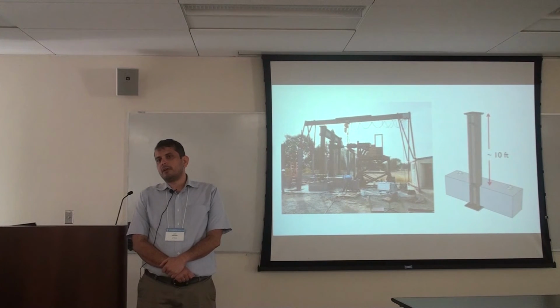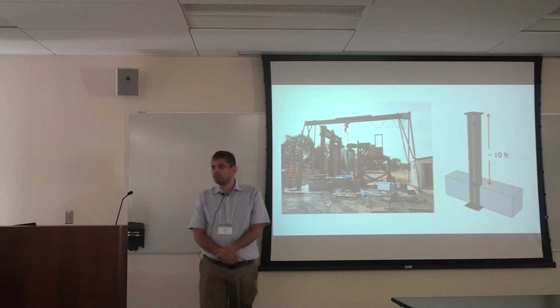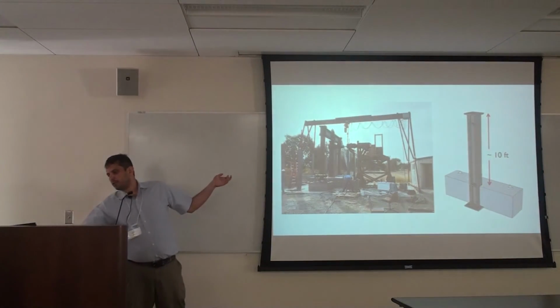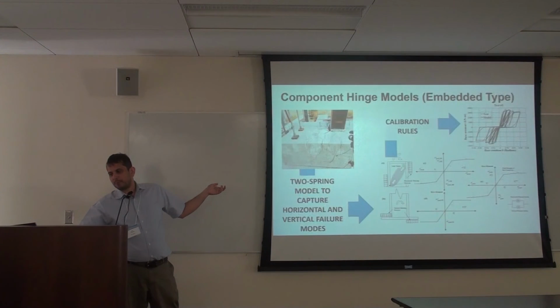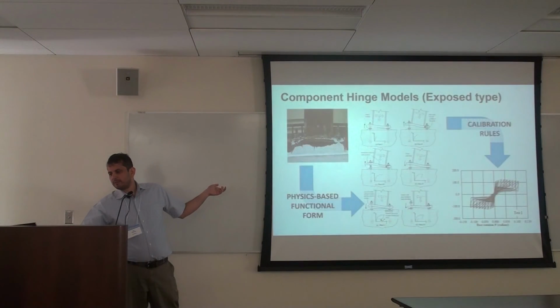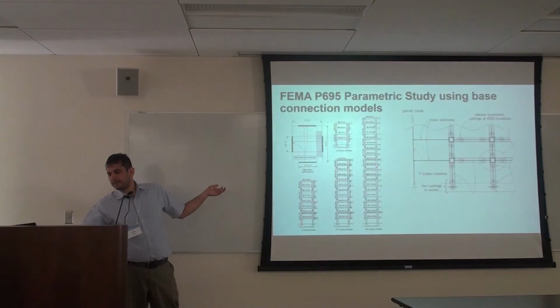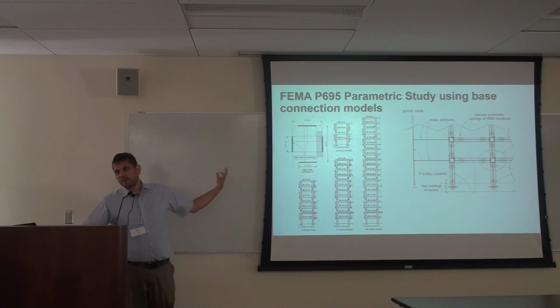Airports are lower rise structures. In terms of the actual clear spans, our 4-story frame isn't significantly different from what you would have in an airport. I think it's a 30-something foot span in the airport, and our 4-story frame is pretty consistent with that. And for that, we actually find that the effect of having the weaker bases is the least detrimental.